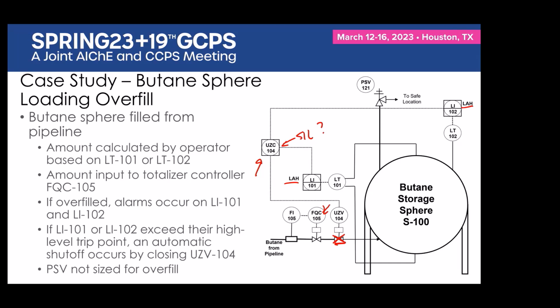So if you're in a LOPA, 0.1 is a conservative number to use in a given scenario under all of those constraints that I just listed out for the taxonomy. When you go into fault tree analysis, now you have more flexibility to look at what the specific scenario is.